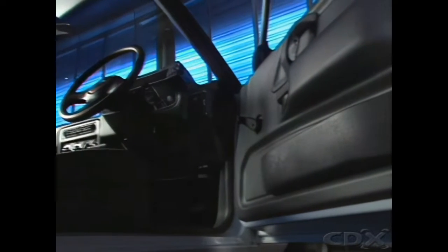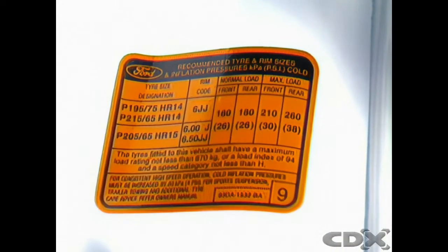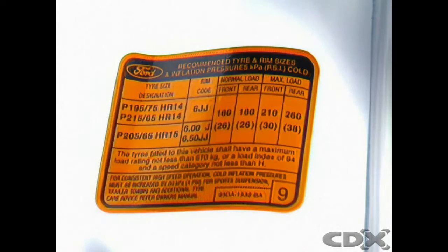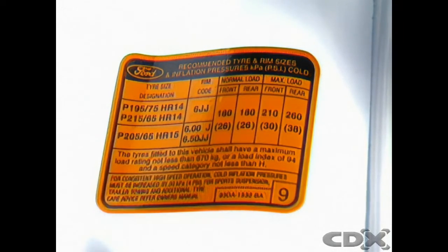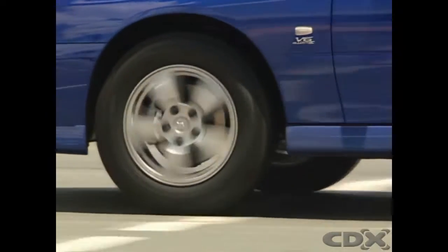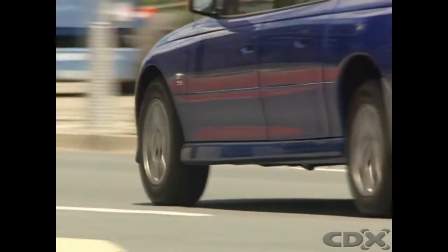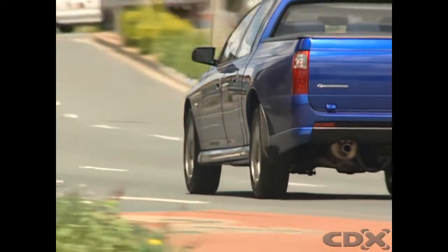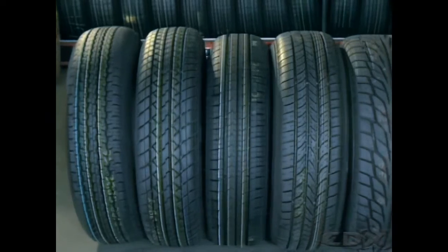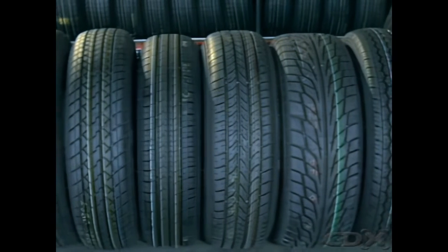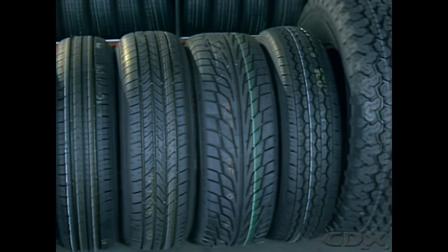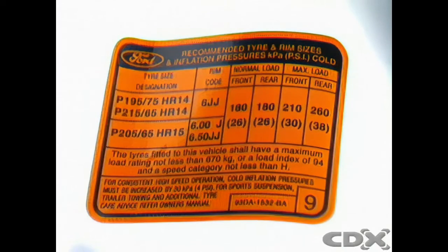Regulations cover the allowable dimensions for wheels and tires on a particular vehicle. These dimensions are usually set out on the tire placard attached to the vehicle. Incorrectly selected wheels and tires can overload wheel bearings and change steering characteristics. The tire placard lists the wheel and tire sizes approved by the manufacturer for the vehicle. Using other wheels and tires may be illegal.